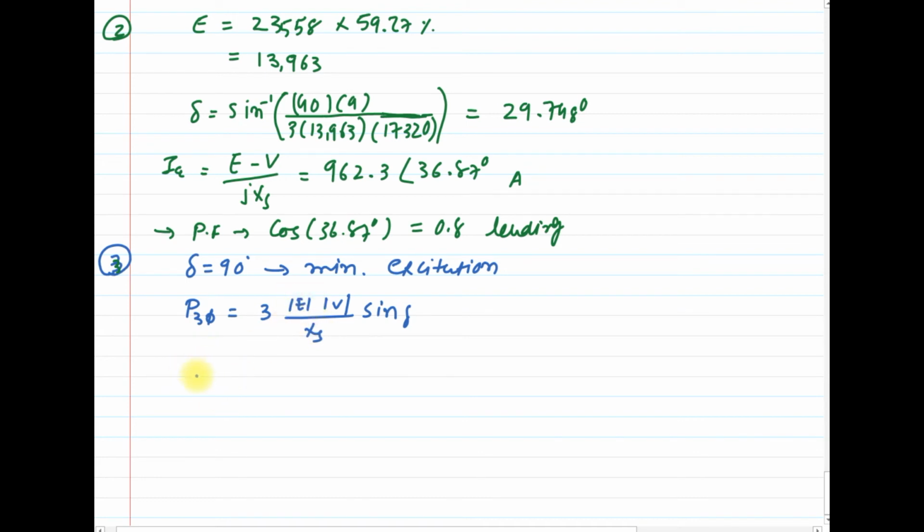So I will write the equation for E. E is equal to P Xs divided by 3 V sine delta.